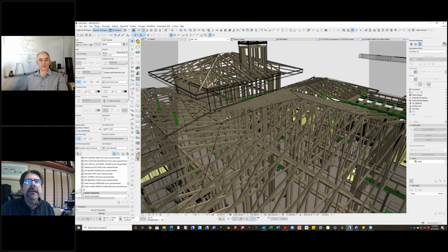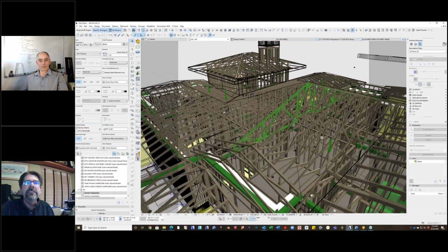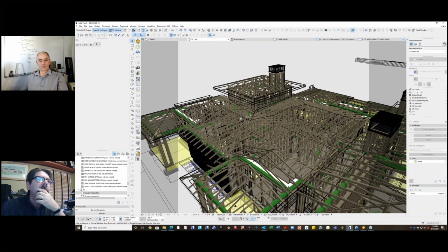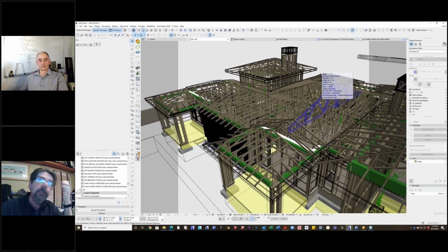And so what's the benefit of that? If you can see through the screen, you can see a little hop in the bottom chord. You can see a pitch coming down, and I sketched in a most likely webbing scenario, even though I know it's not how it's going to end up. But what it does give me is something in section that will help me analyze, if I need a 20-inch trunk line going through there, do I have a spot for that, or am I going to have to tell them to do something special?